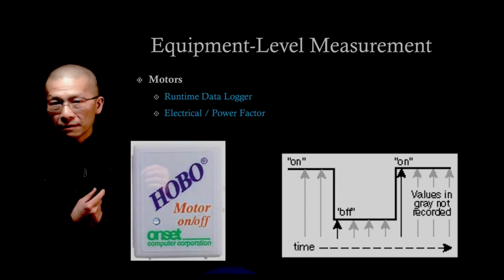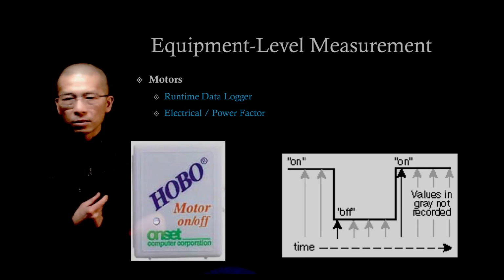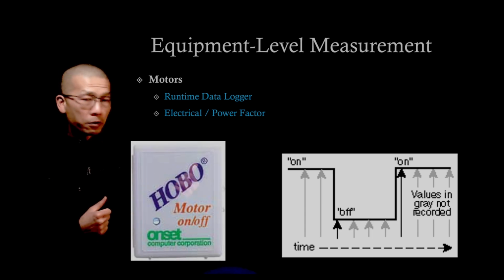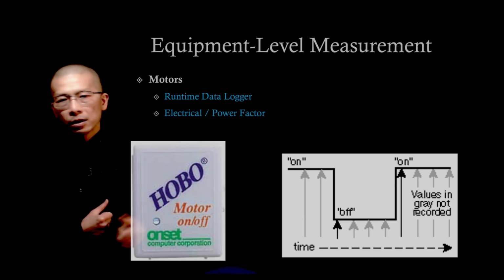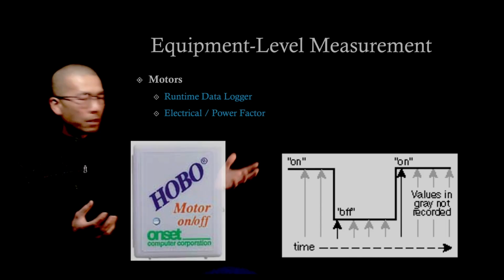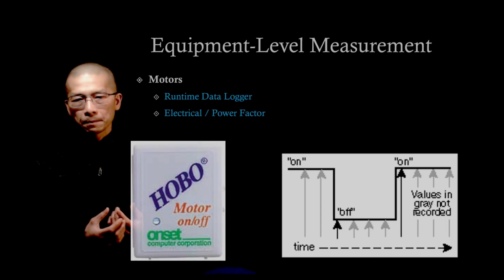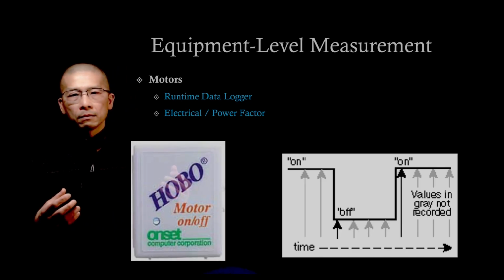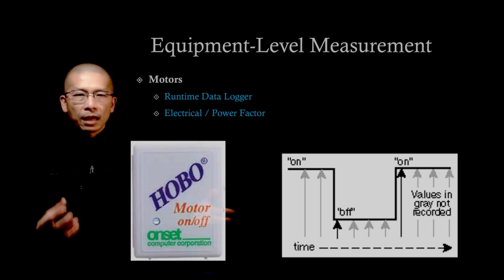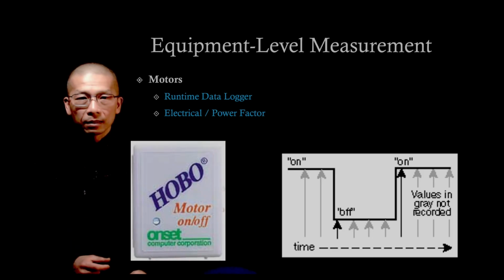It can even help us find mechanical problems as well, like misalignment and overloading, right? And of course, the power factor. That's what we want to monitor as well. It shows how efficiently the motor uses electricity. Low power factor means the motor is drawing more apparent power than necessary, and increases the losses, sometimes triggering the utility penalties that we saw earlier in the previous modules.